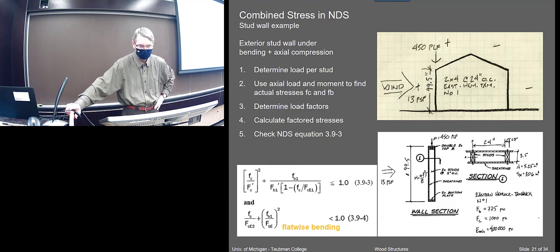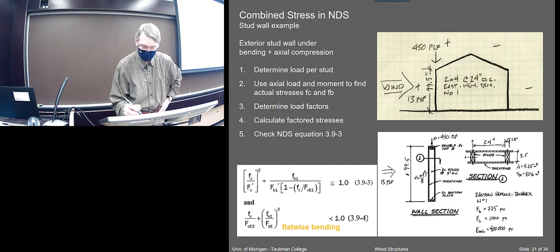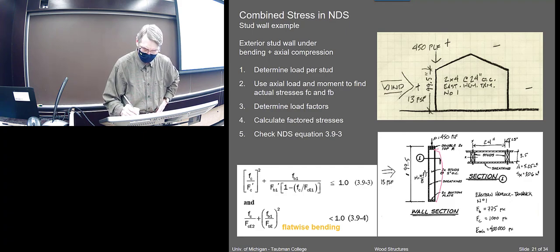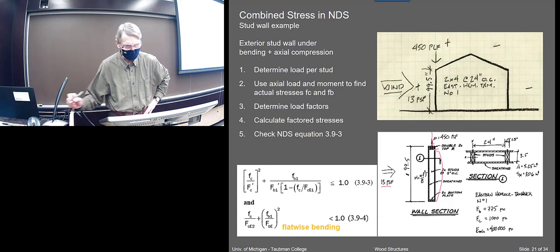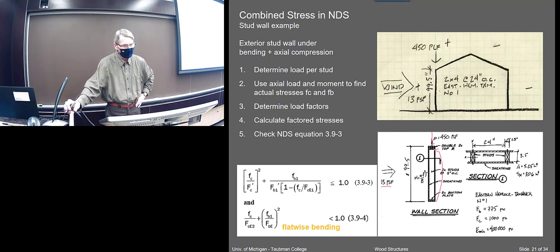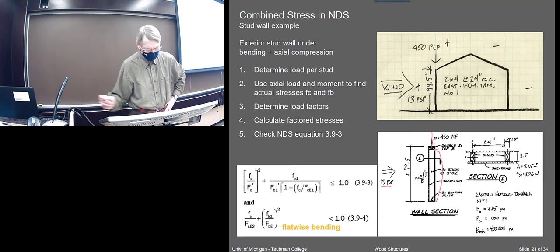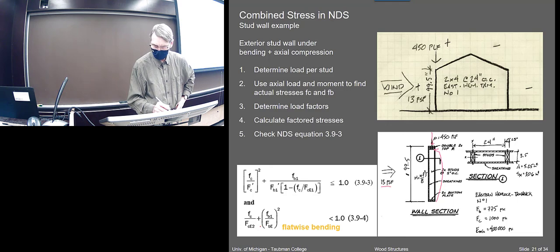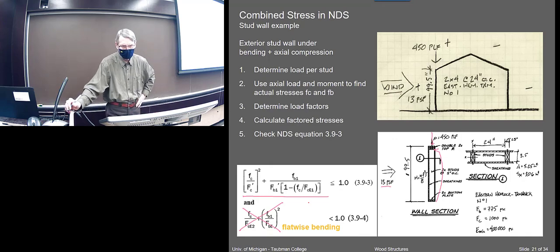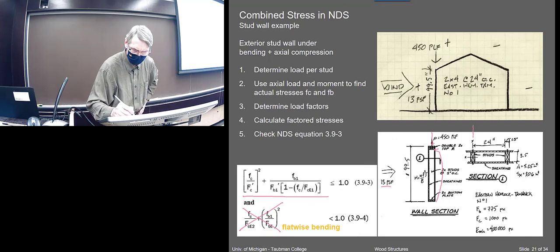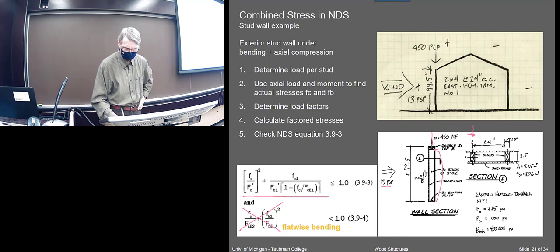But it's pretty much the same. It's looking at flexure, right, due to the wind load, and compression due to, I guess, whatever's on the roof. Something's on the roof. And so we should not have flatwise bending. I don't think that's in this. It should, again, just be these two. Right, because the bending is being loaded like that.